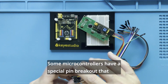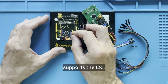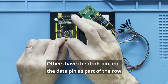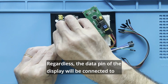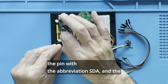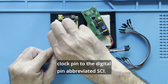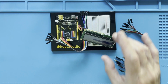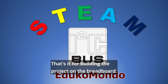Some microcontrollers have a special pin breakout that supports the I2C. Others have the clock pin and the data pin as part of the row of digital pins. Regardless, the data pin of the display will be connected to the pin with the abbreviation SDA and the clock pin to the digital pin abbreviated SCL. That's it for building the project on the breadboard.